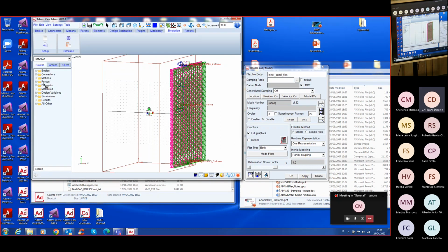I approximate the coefficient of the torsion spring considering the gradient of the curve. So I evaluate approximately the stiffness from the graph in the linear range, but it's an approximation only for methodology. It is not very precise. I get the graph and I evaluate, let me say, the tangent, okay?